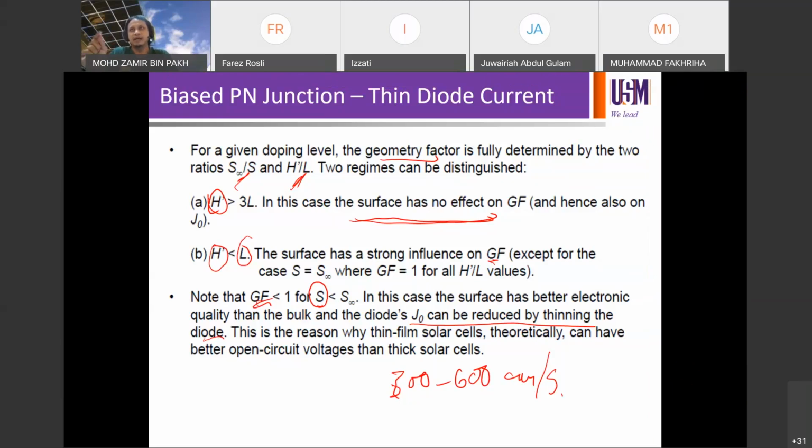For a solar cell, you have short circuit current, open circuit voltage, fill factor, conversion efficiency. But for an integrated circuit, you have drive current, rise time and so on. So it's a totally different set of parameters. It's hard to give a single answer as to which is better, thick or thin. It really depends on which application we are talking about.